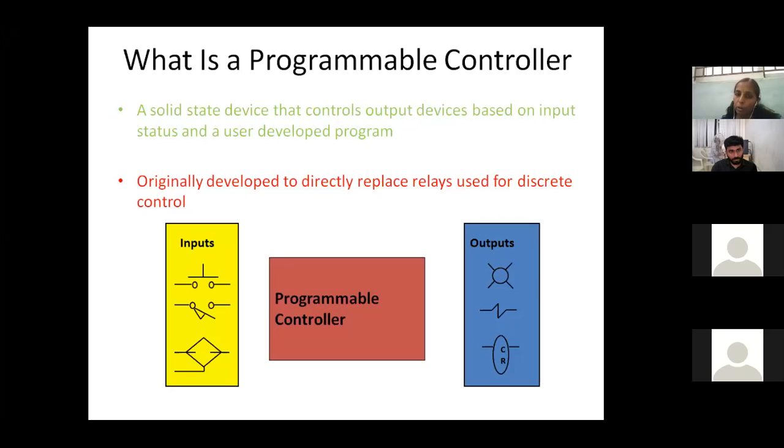In all controller functions, you will finally be performing only arithmetic and logical functions. For example, you are going to measure two sensor inputs, temperature 1 and temperature 2. You have to find the temperature difference and which one is greater, and based on that, turn on some output. So this is what you can do. In order to compare this, you have to perform a compare function, or a subtract function.